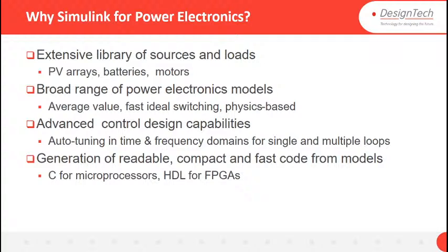Why Simulink for power electronics? In MATLAB and Simulink we have extensive libraries of sources and loads like PV arrays, batteries, and motors. A broad range of power electronics models is available, like average value, fast ideal switching, and physics-based, and also converters, motors, and machines. The libraries are already available there. Then there are advanced control design capabilities. Controlling power is very important when you are designing a converter, that is, how you are going to control the output from the electrical system, the power system, right?